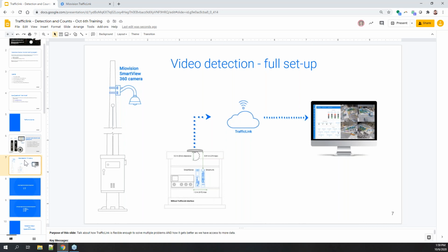Thinking about the height of the camera, it sounds like you understand the table a little bit there of height versus distance. Generally at 30 feet high, the camera can get you a front of the stop bar zone at 150 feet, stretching back to about 190 feet. So it gets you a nice 40-foot range to play with. So hopefully that answers the question.